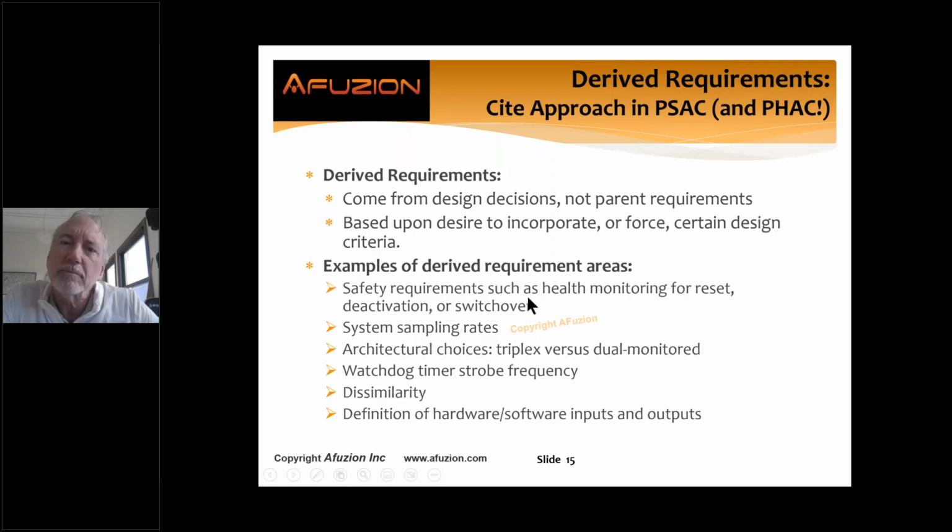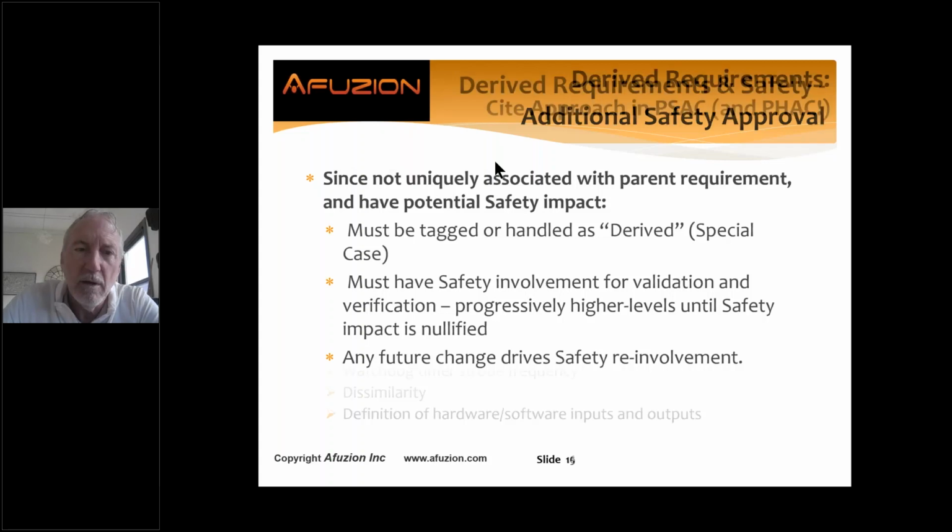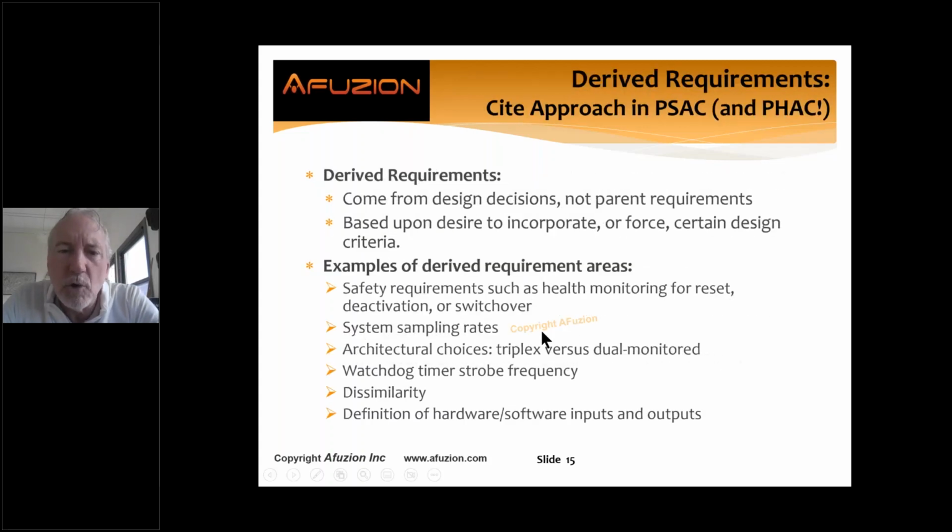Safety requirements, health monitoring, deactivation, switchover. How fast do I poll? Am I 50 hertz, 20 milliseconds? What's my architectural choice? Triplex or dual monitor? Do I have a heartbeat? Do I cross monitor? Do I self monitor and share? How do I notify system level that I've reset, or should they reset me?